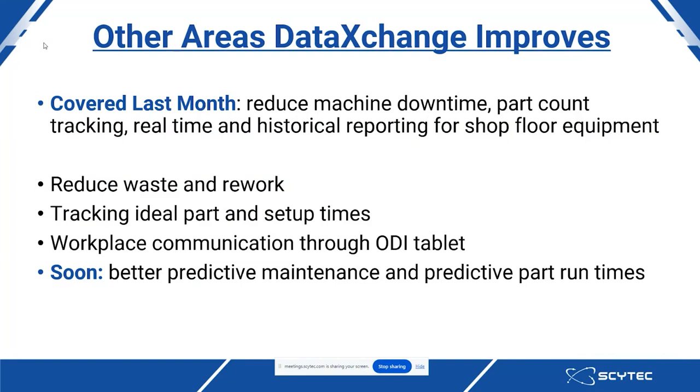Now, last month, I also talked about the ODI tablet and what that can do to improve your shop floor performance. What you are gathering from a machine automatically is not going to tell you every single thing. You will have to have your operators elicit some information that could be extraneous to what is going on inside of the machine. Like, an operator goes for a lunch break or a bathroom break, or a carbide broke or something like that. They can enter that information into the ODI tablet, and that can also make sure that your OEE information is not skewed. You're getting the most accurate information possible.